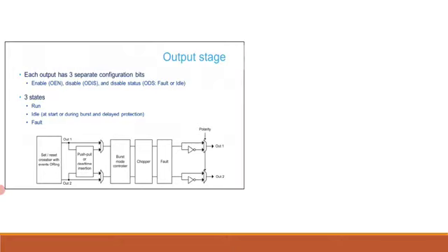The burst mode controller allows both outputs to be automatically disabled and re-enabled for a limited period of time. The chopper unit can superimpose a carrier signal on top of the active PWM waveform. Finally, the fault stage can disable completely the output to protect the power switches. The polarity is programmed at the end. The entire HR timer waveform can be programmed by just reasoning in terms of active or inactive switches, independently from the external gate driver and or interface sensitivity, before the polarity is applied.